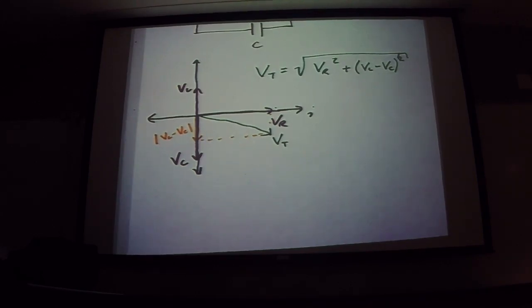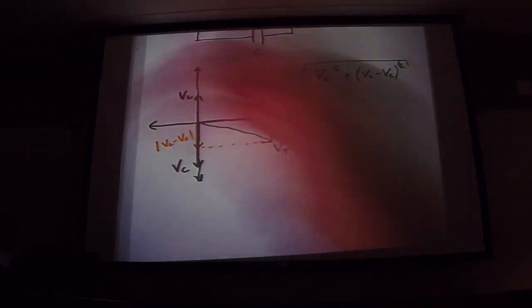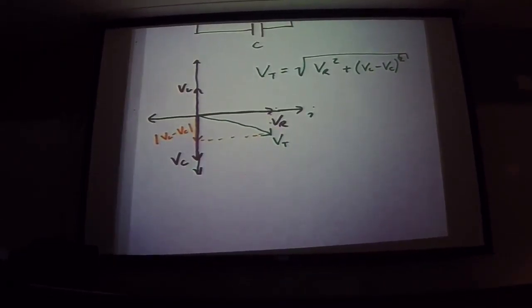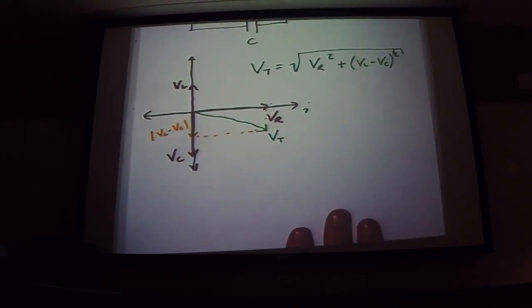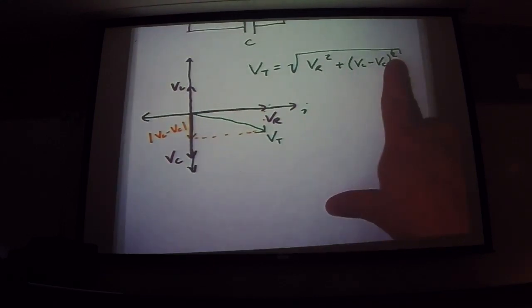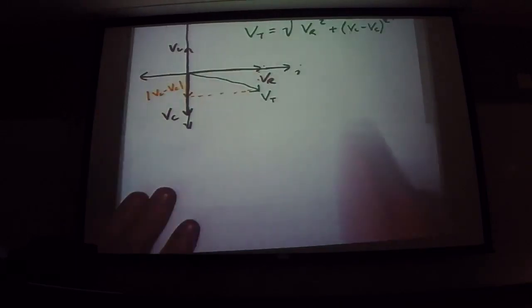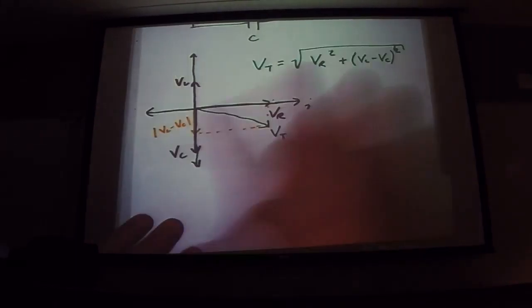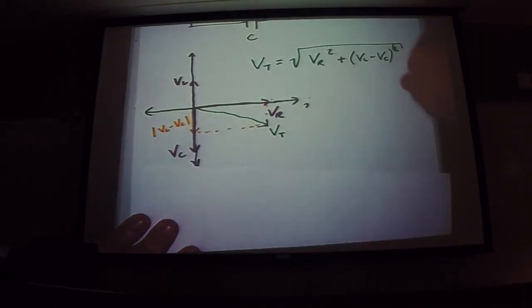Okay, well now let's take our diagram, and we're going to divide every term here by the RMS current in the circuit. Is that 1/2 at the end? No, that's squared here, and it's under a square root. In other words, it's the vector sum of the two. This side squared plus this side squared, square root.